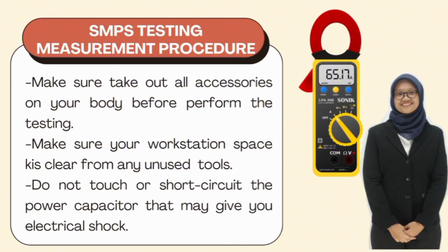First, make sure to take out all accessories on your body before performing the testing. Next, make sure your workstation space is clear of any unused tools. Lastly, do not touch or short circuit the power capacitor, as it may give you an electrical shock.